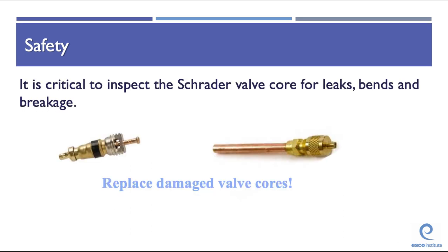When using recovery cylinders and equipment with Schrader valves, it's critical to inspect the Schrader valve core for leaks, bends, and breakage. Replace damaged valve cores to prevent leakage, and always cap Schrader ports to prevent accidental depression of the Schrader valve core.